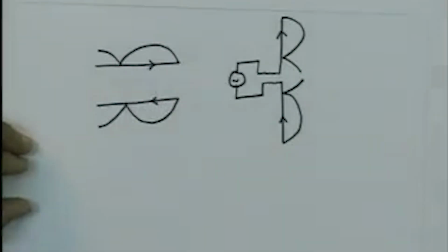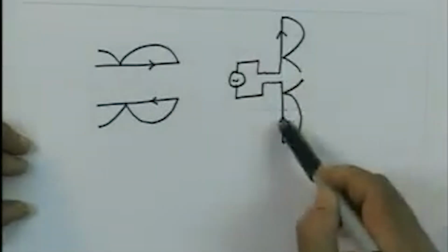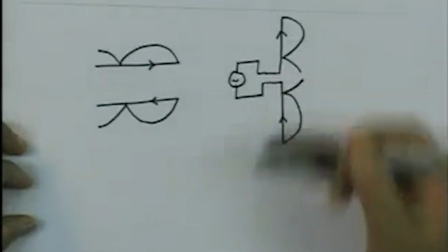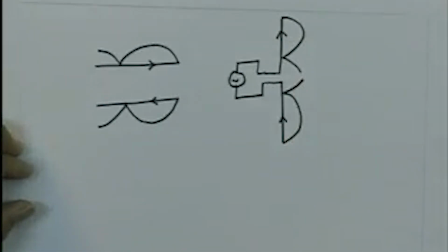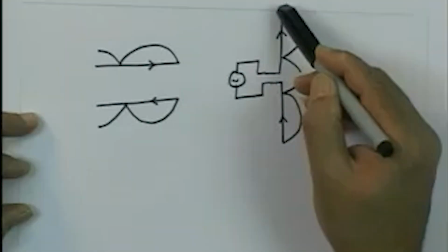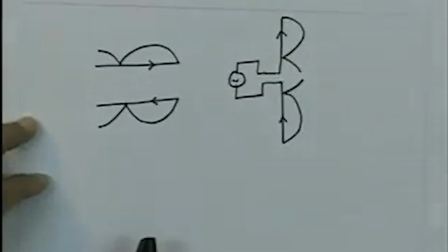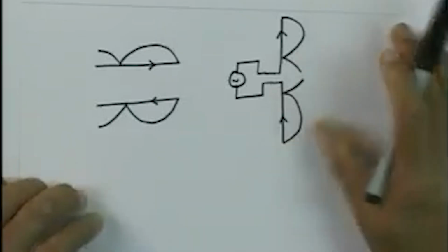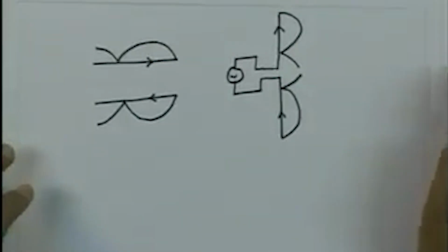However, when you have a flared up version of this, the currents travel in the same direction. So, you have a symmetry of the current distribution on the dipole, and you have the current 0 at the tip of the dipole. These are the two conditions under which one can investigate the problem.